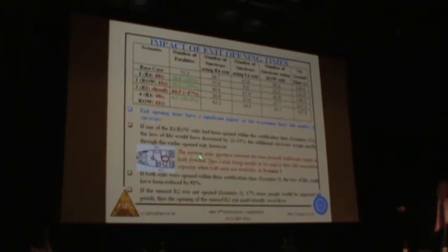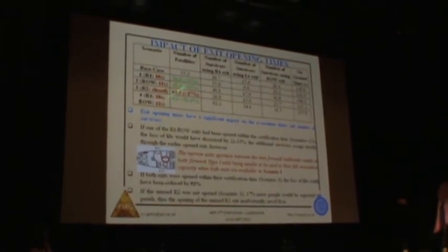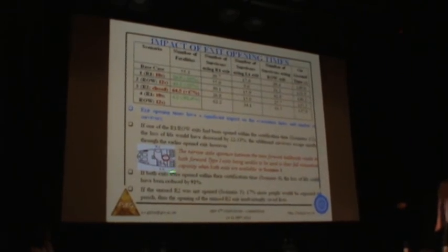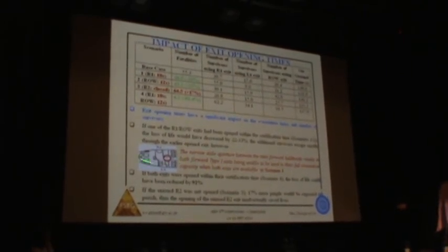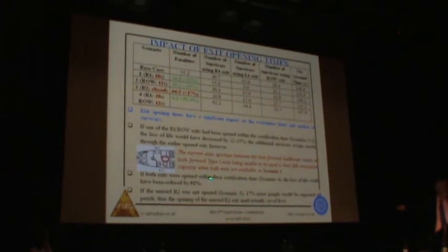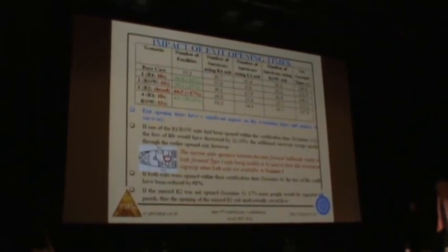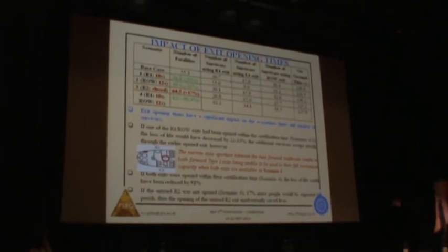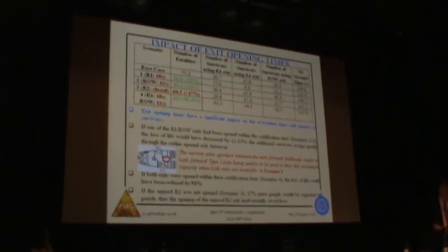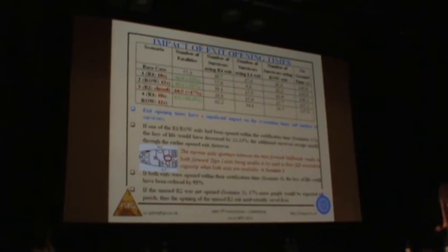The other thing that's interesting in terms of the results, even when you have both these exits open, the aisle cannot provide a flow rate great enough to keep both exits open. So when you have both exits open, you don't get the full advantage of having both exits open because the aisle can't feed the passengers in quickly enough to support both exits. So it's a fundamental flaw in the design of these aircraft. Not just this aircraft, but all aircraft.